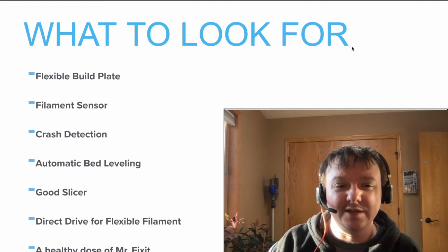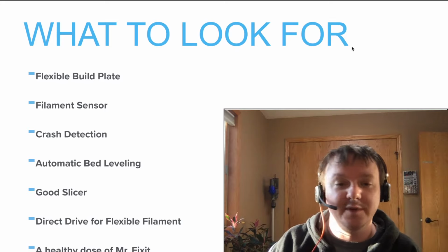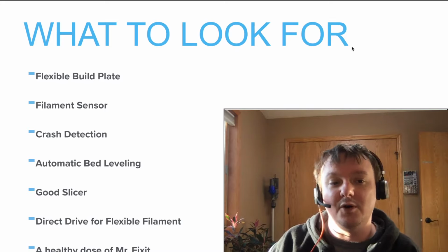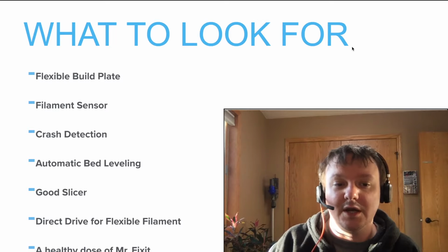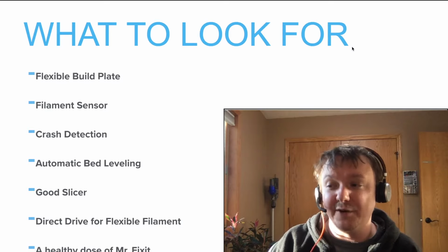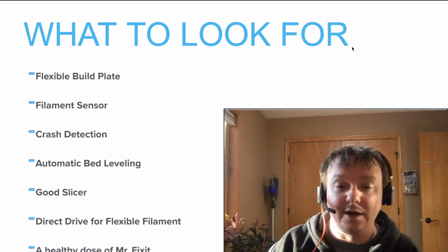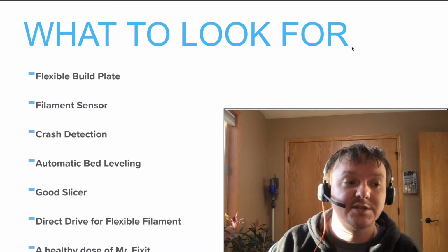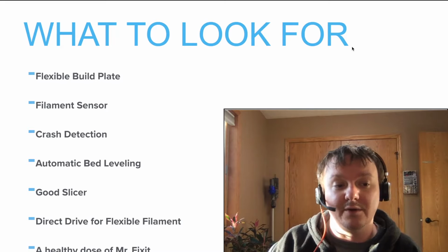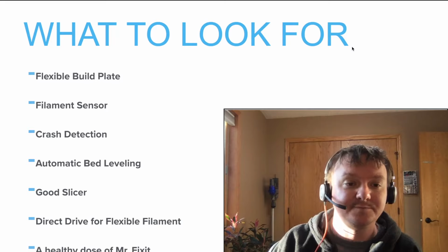Crash detection is relatively new, but this will figure out if it's running into something. It could be a human, or it could be your part came off and it's running into the side of your part. That's also a great feature. You want to make sure that it won't catch fire. Some of the very cheap 3D printers are known for catching fire. I keep a smoke detector near my printers just in case something goes wrong. They put out a couple hundred watts of heat. That's enough to catch plastic or various other things on fire.